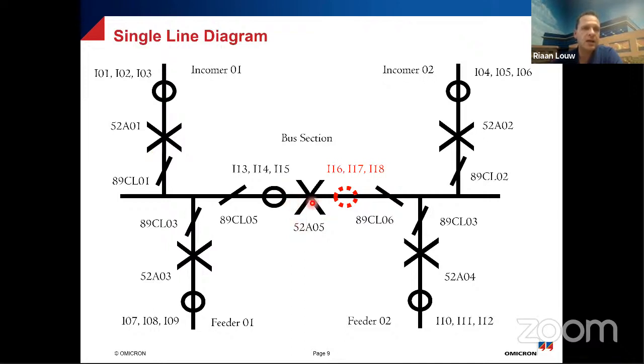And in that case, if the fault was here, zone 2 would have immediately tripped. And if the fault was still there, obviously it would have been because the breaker is now open, I'm still supplying a fault here, then I would still have this feeding that fault, and then I would trip zone 1. And that's if you select speed as a priority.